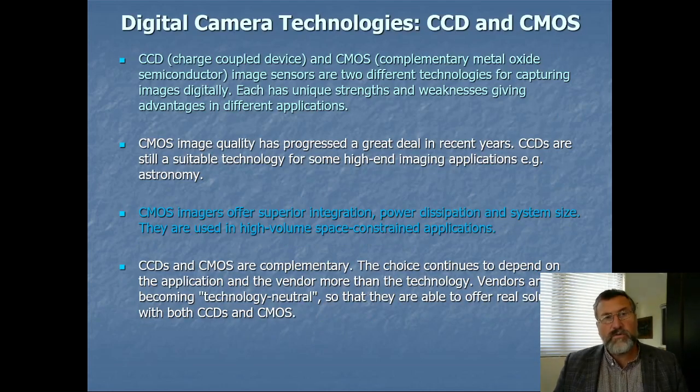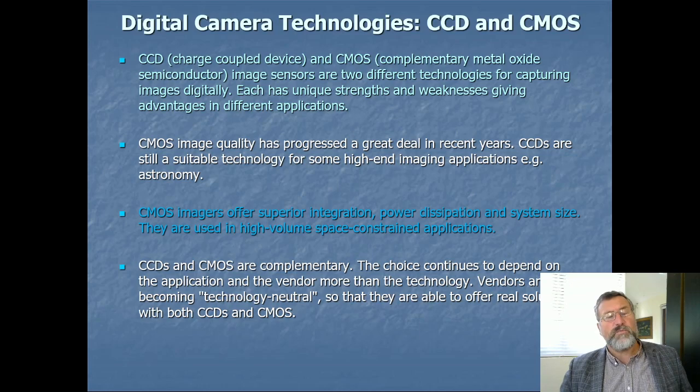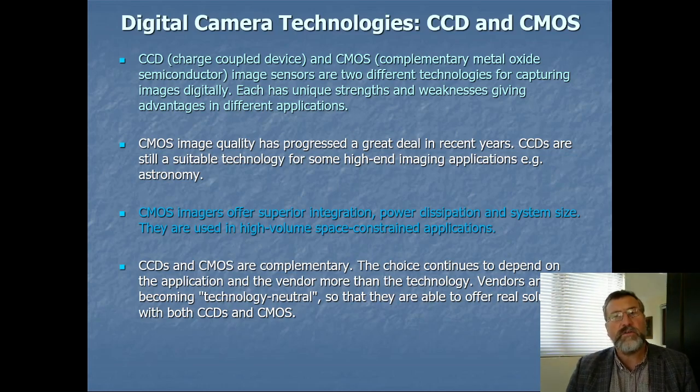You can use different resolutions of cameras, and when you buy a camera, you normally are thinking about resolution. You're thinking about megapixels, aren't you? But actually, when we're in machine vision, we're not necessarily requiring very high resolutions, because if you have a very high resolution image, you need a lot of processing just to do a filtering operation on it or something like that. So it's important not to have more resolution than you need. We find a lot of the time that 5 megapixels will give us enough resolution for many applications.